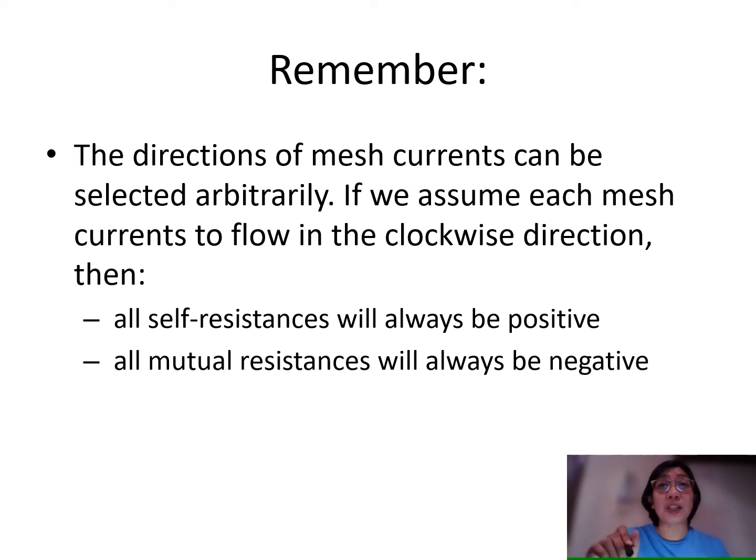Remember this: all self-resistances, what do we mean by self-resistances? When we are talking about mesh number 1, all of the resistances where mesh number 1 current is flowing, we always treat as positive.